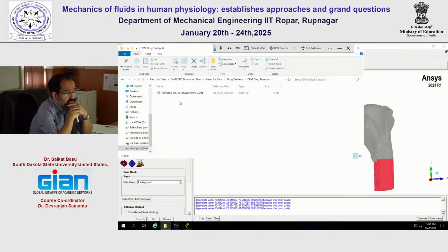Now, for example, if you are looking at red blood cells, they are not spherical, right? So you can use user-defined functions to tell Fluent if the drag force formulation needs to be changed. There is a shape factor as well that you can control for those applications, but we don't need to worry about them here because we are assuming the particles to be spherical, and that is the default. It would assume that whatever the diameter is, the 10 micron is the diameter. It is a spherical particle, and it would calculate the drag accordingly.